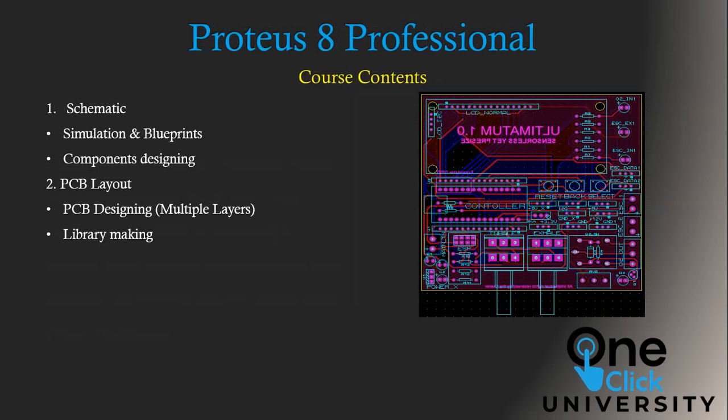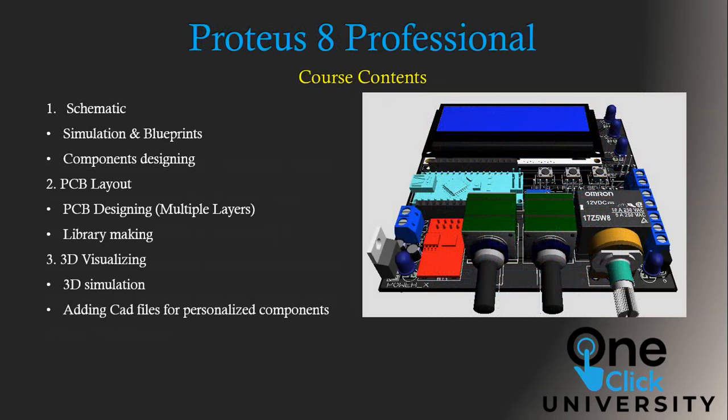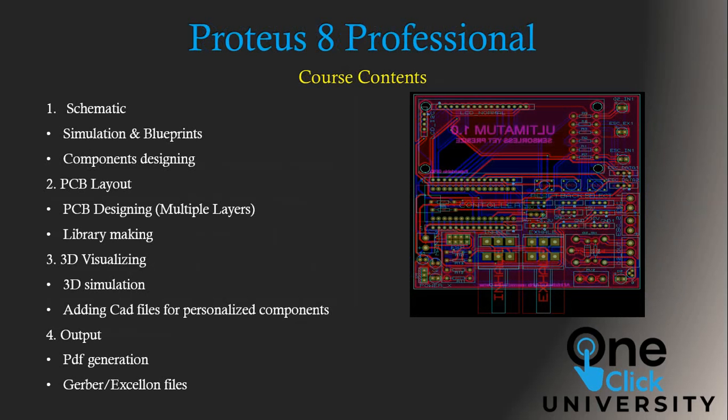After the PCB is designed, the 3D simulator helps checking how the PCB will look with and without the components, the color in which the PCB is going to be made, and the spacing of the components. Everything can be designed more precisely by looking at the 3D simulation. Then finally, we'll learn how to take the outputs, creation and viewing of Gerber files.